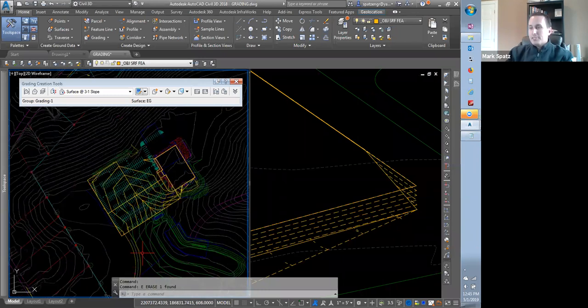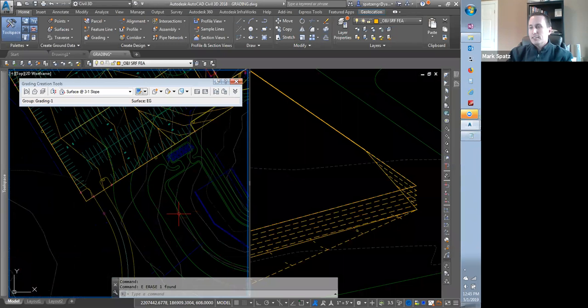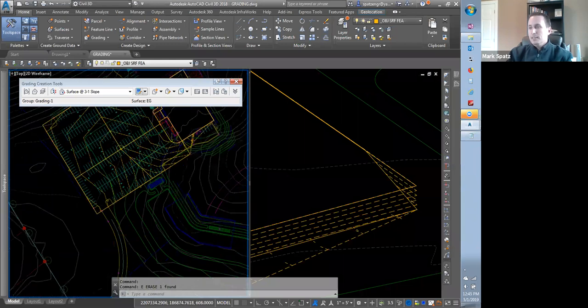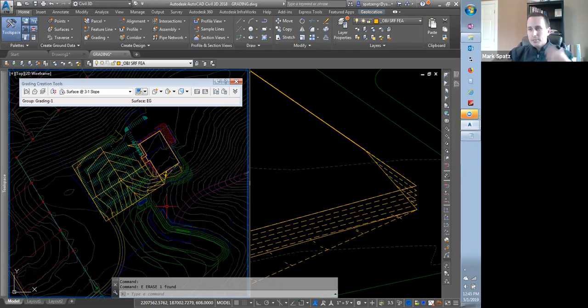Coming up through here, obviously you'd have a corridor. Coming through here, you'd obviously establish the top of berm. You'd daylight down on both sides of the top of berm. Here, you would just let this grade in between your corridor model and your top of berm. It's a little bit of a process.